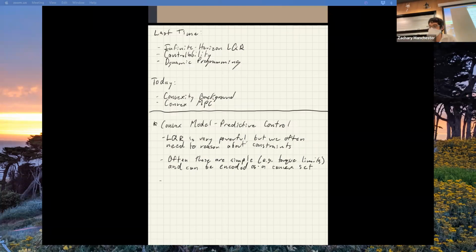And then basically the message is that constraints break this nice Riccati LQR solution that we've been talking about. But if I'm thinking about this as the QP formulation of LQR that we talked about before, QPs can have linear inequality constraints. So I might not be able to use the Riccati solution and the nice K matrix, feedback gains, but I can still just go solve the QP.